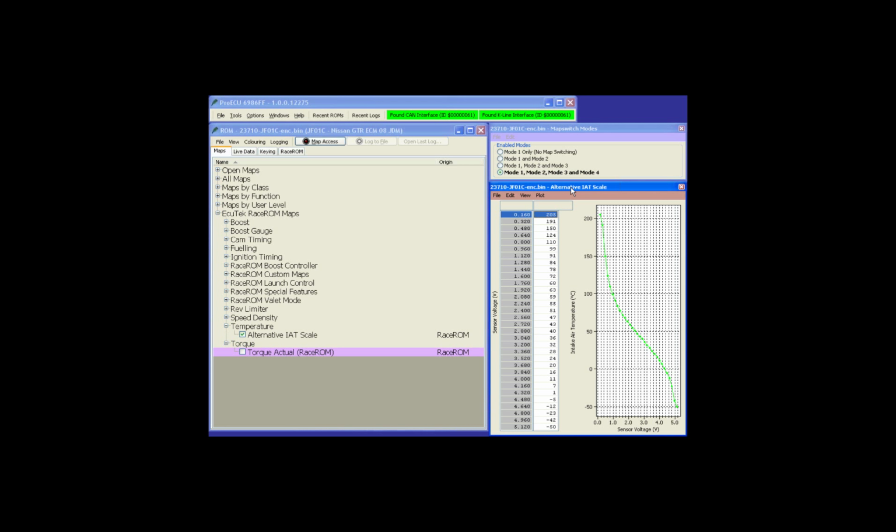You can use a Nissan Duke boost pressure sensor in the charge pipe that will replace the factory boost sensor and incorporates very nicely an intake air sensor, a charge air sensor as such. Using the plug-and-play looms, you can replace the intake air sensor with a charge air sensor. Alternatively, you can put a separate standalone charge air temperature sensor into the engine ECU. There's a specific sensor input that we can use to import it. I think it's a fuel temp sensor pin that's not used on most models. So we can import a new intake air temperature sensor.